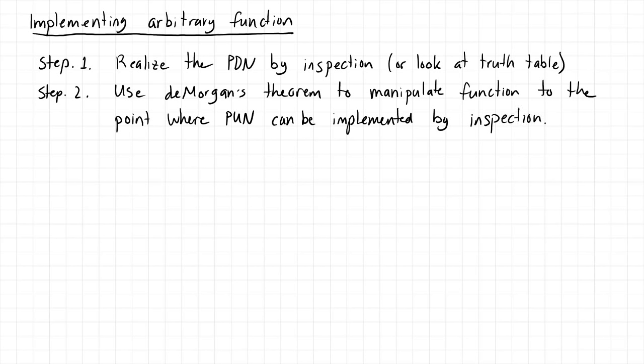Okay, so again, you might be thinking, well, Professor Mercier, that's not terribly useful. You're basically just telling us to do it. Bear with me. I think it will eventually make sense, particularly when we go through an example. Okay, so let's go through an example. F equals A or B and C, all inverted. Okay. So it turns out that step 1 is actually fairly easy once you wrap your head around it. Okay. So let's synthesize our pull down network. Okay, so we have A, or, B, and C.